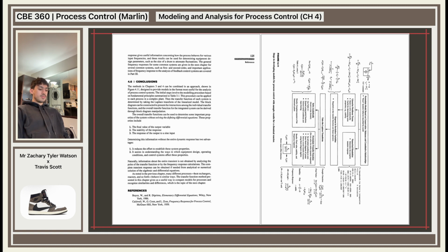The overall transfer functions can be used to determine some important properties of the system without solving the defining differential equations. The properties include the final value of the output variable, the stability of the response, and the response of the output to a sine input.